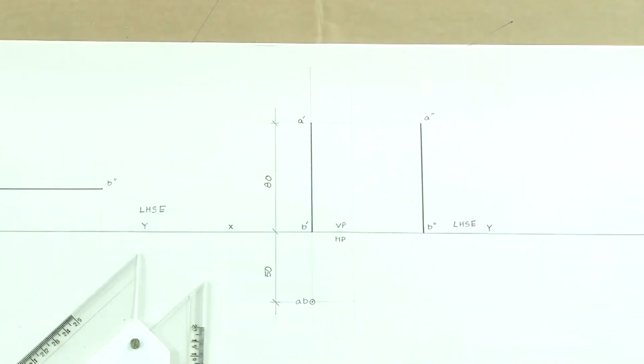And another thing that we have to understand is that we only mention the true lengths of the objects which are being projected. Suppose this line was inclined, and instead of 80 mm, we were seeing just 60 mm in its projection as a trace. We will not dimension that. Anything which is not seen in the true length or the true dimension will not be labeled, it will not be dimensioned. That is what the rule of graphics is. That is another rule. So, that is one condition.